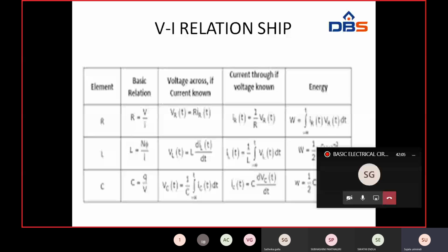There is no need to change the voltage sources because their polarities do not change, only the passive elements change. So depending upon the passive elements, there must be 5 resistors. For these 5 resistors, we observe that where the current enters will be positive, leaving will be negative. R2 entering is positive, leaving is negative. For R3 entering is positive and leaving is negative.